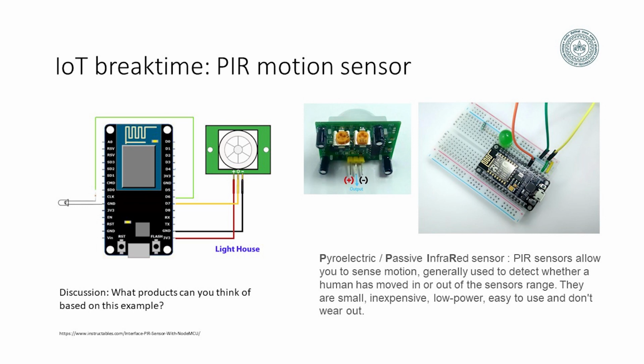So, based on that you will be able to identify the plus and the minus, and then you need to set it up. In this case I did not use a resistor across the LED, but it is suggested that you use the resistor, otherwise the current through the LED will be quite high and it will have a shorter life. And then you hook up your circuit, and that is it. Then you need to set your code up, verify it and run it.